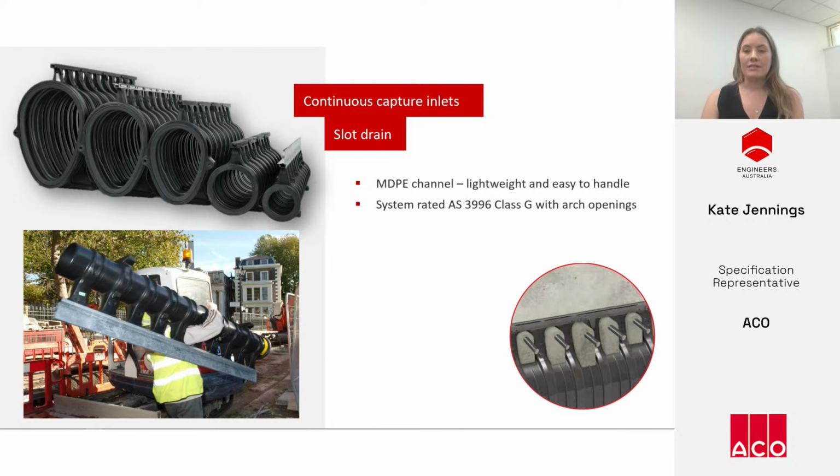Some slot channels are designed to be super strong when they're integrated into a slab. The arch opening, shown at the bottom right of the screen, allows reinforcement to pass through the arches to tie the slab together on either side of the channel without disrupting the line of the inlet slot and allowing for an unbroken reinforced slab detail.